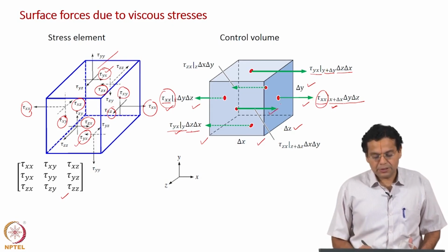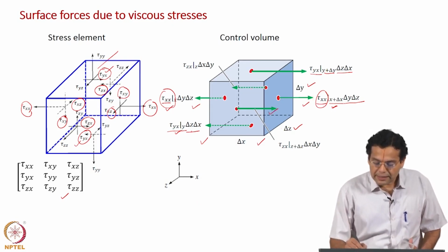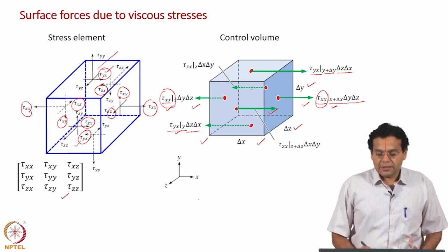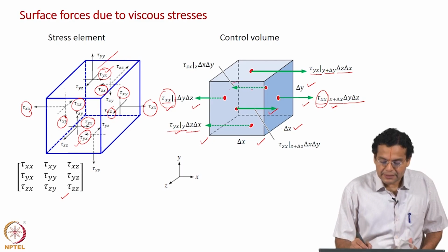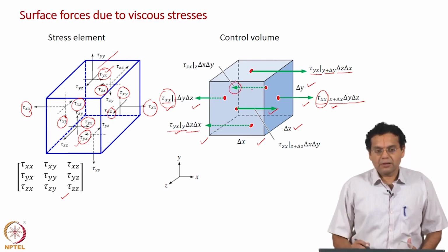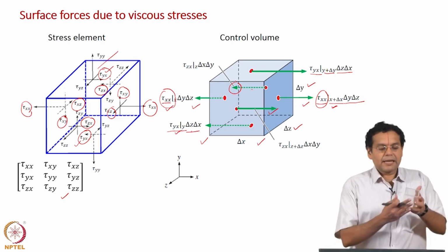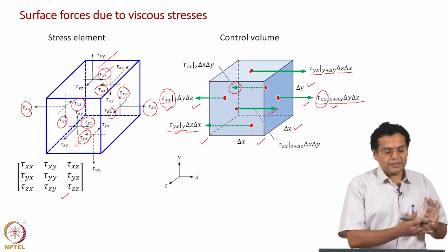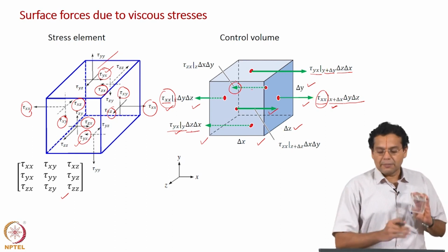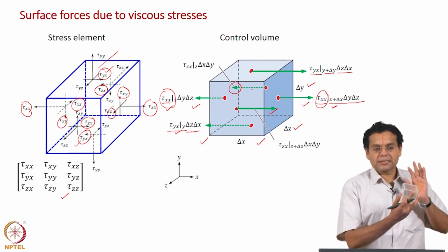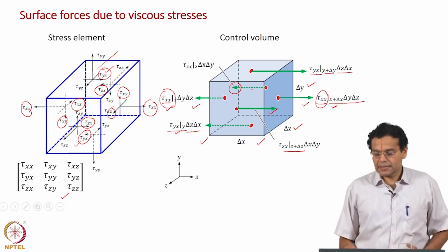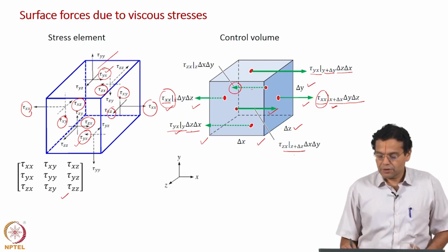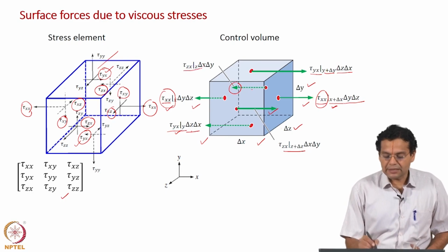On the rear face it is a negative z face, so the force is along the negative x axis. And as we have discussed for other directions, they are spatially separated. In the left hand side figure they are opposite sides of the same face, while in the right hand side figure we have z and then z plus delta z, that is why we have z plus delta z for the front face and z for the rear face.